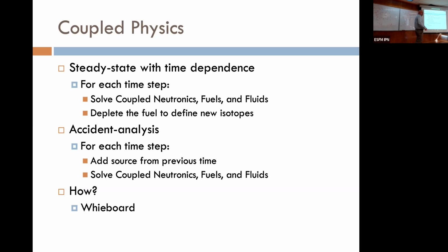But hopefully that gives you an idea of, if you're using Casmo and Simulate, this is what's happening under the hood in all of these different physics domains. So Casmo or Simulate is mainly known as a big neutron diffusion solver, but it has inside of it a fuel model and a thermal hydraulics model also. And so it can do this full coupled physics inside of it if that's what you ask of it. And that's how it is doing these things and creating these models.